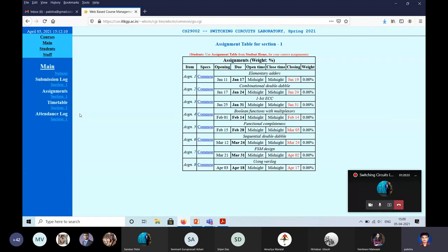And then I'll give you the setup commands. So first you have to compile it. So you have to write iVerilog, I'm just forgetting it. I'll check out. You search Google, you will get it. iVerilog then the .v file. By default, it will make a.out. If you give -o, it will give something else. Then you execute your a.out.